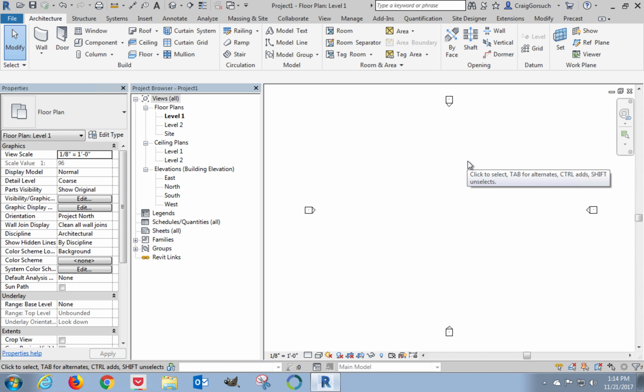We don't have any structural elements. Normally, floor plan grids or a grid on a floor plan is used to indicate where in the plan structural steel framing is being used. In this case, we're using them as reference go-bys for major portions of our house to be drawn at.